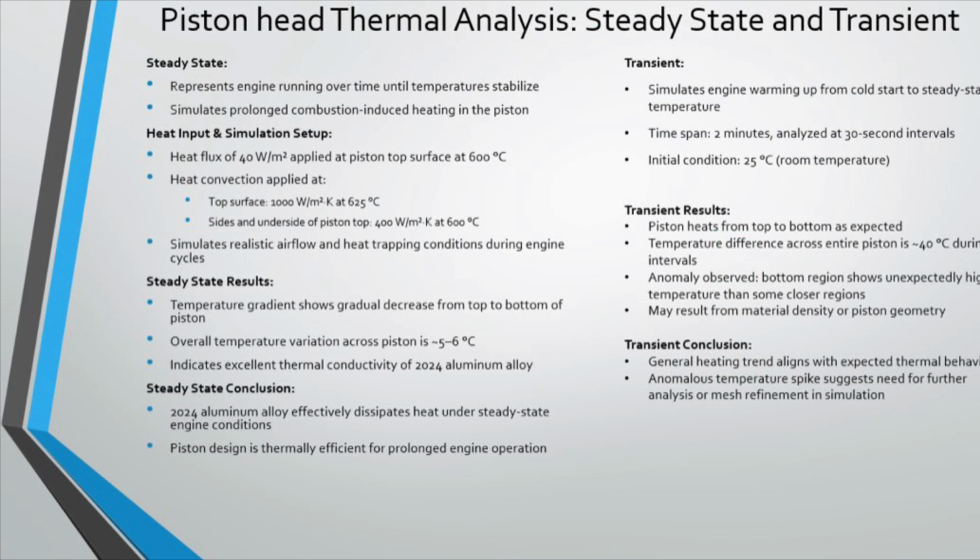Piston thermal analysis: both steady-state and transient cases were studied. While the steady-state case represents the engine running for long periods of time with stabilized temperatures, the transient case reflects thermal loads over a short period of time when you turn on your car. For this case, the piston head was initially at room temperature, while the thermal loads were applied through a 2-minute time period, in this case with 30-second intervals.